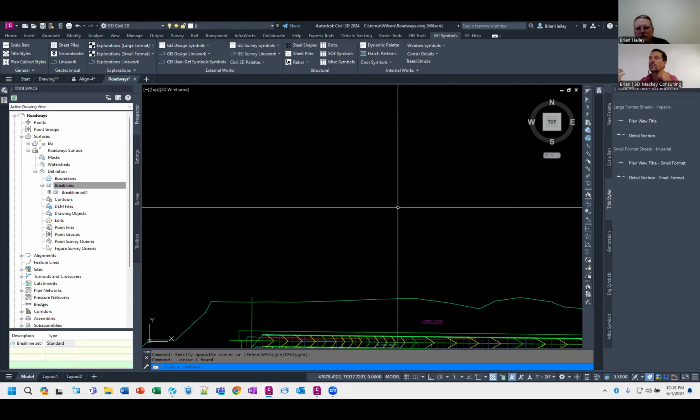Like I used to overwrite the dimension tools, so if somebody went to the dimension tool it was actually going to my lisp routine, which would switch you to the correct layer before you did the dimensioning. So even the dimensions went on the right layer, etc. Just things like that, I think, become the biggest time savers out there.